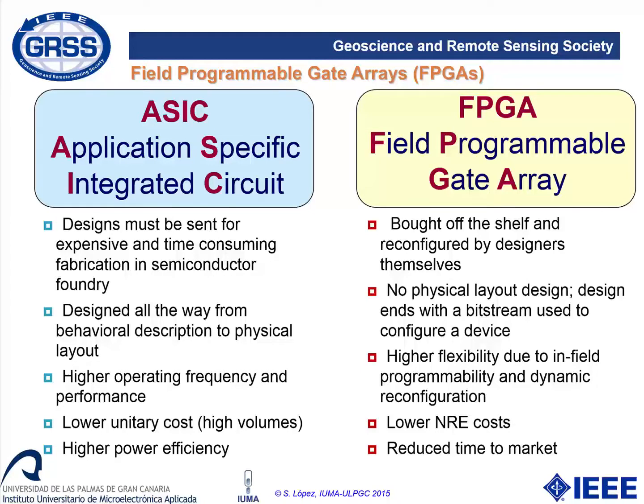But the main drawback is that with an ASIC we can only do one thing, while with FPGAs, which are basically programmable hardware, we can reprogram the hardware every time we want and run different algorithms on the same piece of hardware. Of course, we are not going to get the same performance levels as ASICs, but right now with modern FPGAs we get, I would say, close levels of performance, and we have of course the advantage of reprogramming.